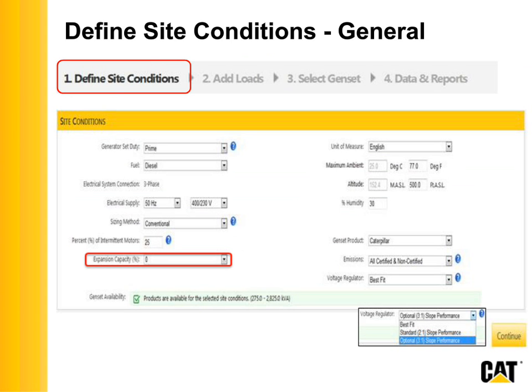It's not just straight linear loads, it's not just straight motor loads. So we allow up to 30% capacity, and it's important to understand that if your load scenario sizes a genset that's lightly loaded or prone to wet stacking, loaded at less than 30% capacity, this rule will not take effect. This feature will not take effect. We're not going to cause your genset to be even more lightly loaded.